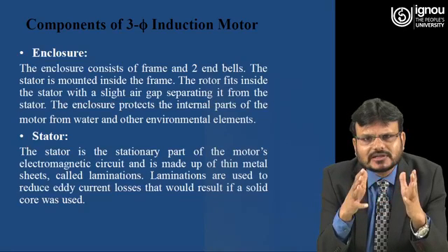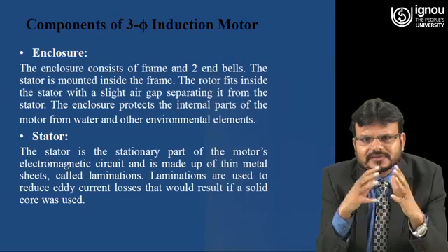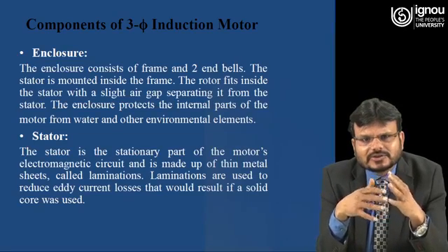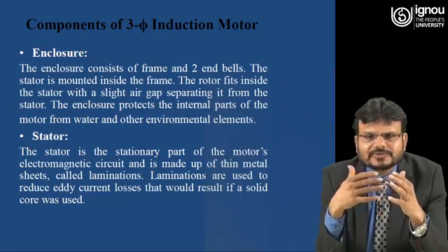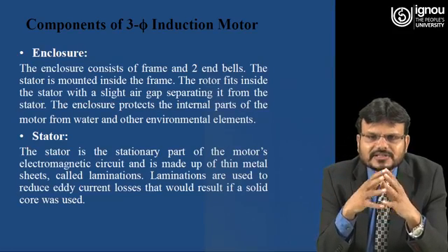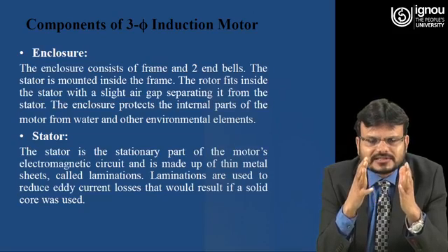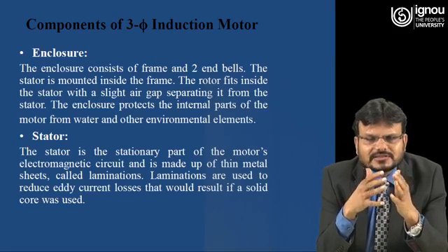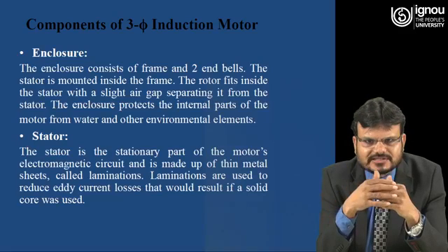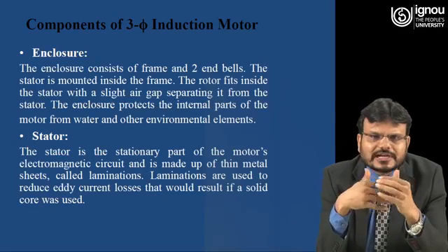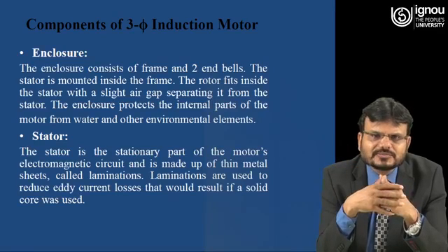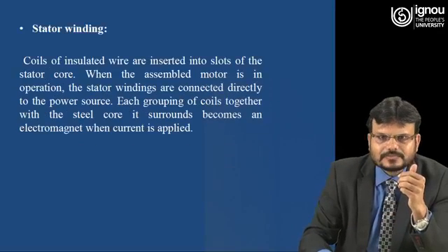The next part of the induction motor is the stator. The stator is the stationary part of the motor's electromagnetic circuit, and it is made of thin metal sheets. What is the use of these thin metal sheets? Basically, by making this lamination you can reduce the eddy current losses. If you are able to reduce the eddy current losses, you are able to increase the efficiency of any machine.